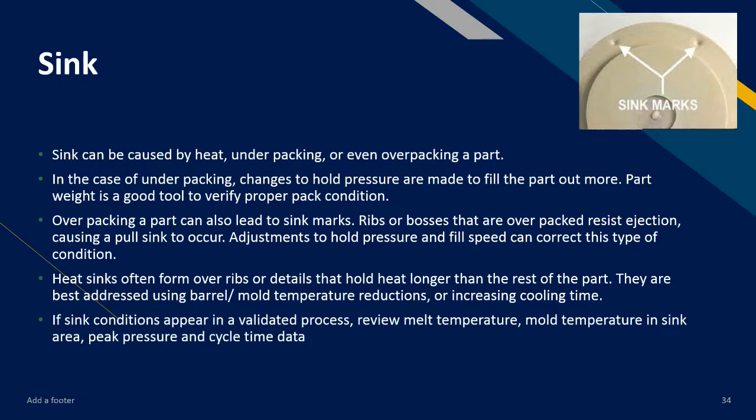Now, if sink conditions appear in a validated process, you would want to review your melt temperature, review your mold temperature in a sink area, peak pressure, and look at your cycle time data.